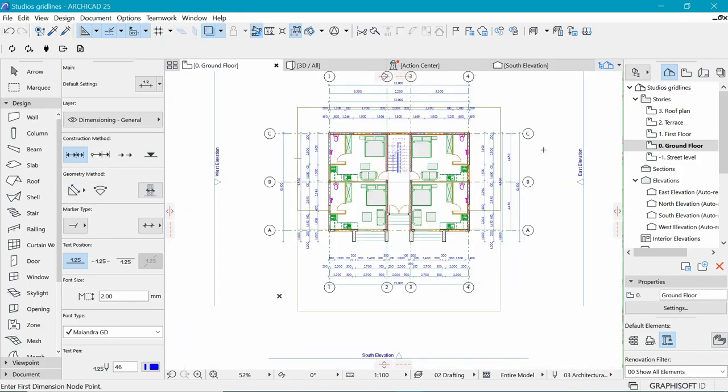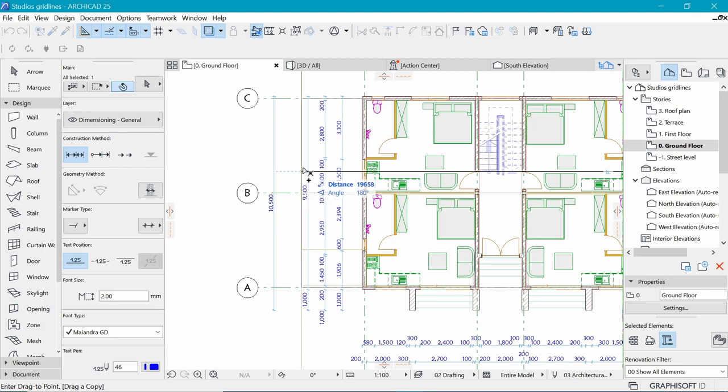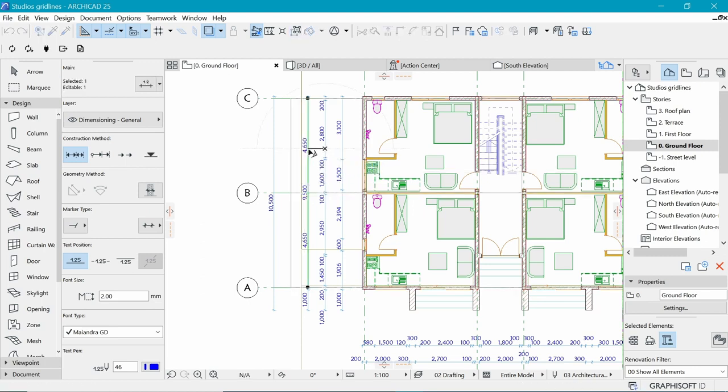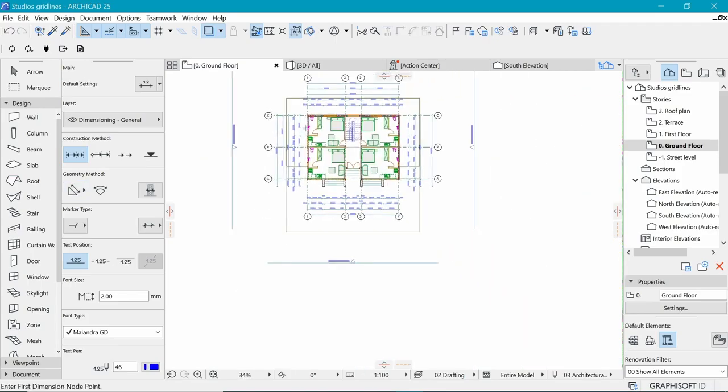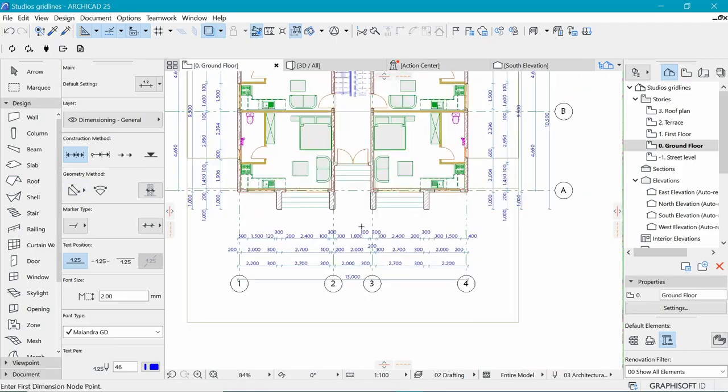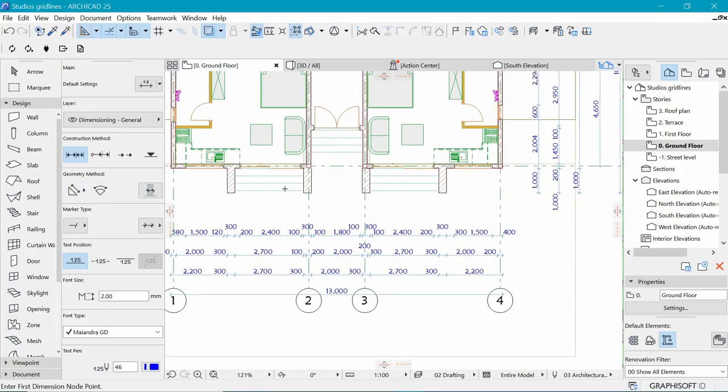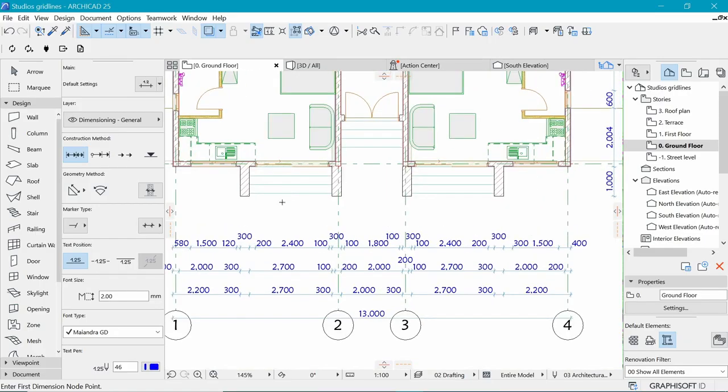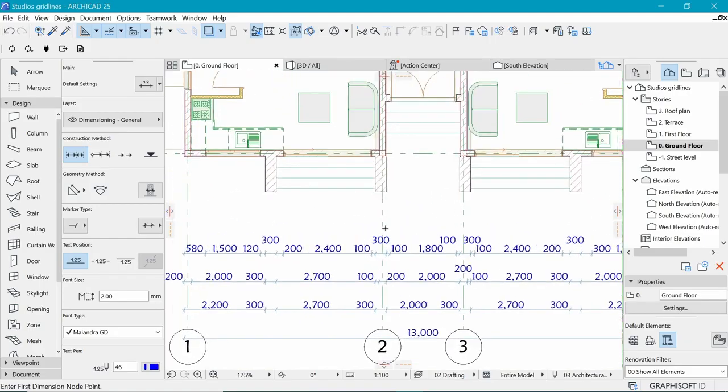So we can actually make a copy of this, Ctrl+Shift+D, in order to drag this all the way to somewhere here. And in order to put it in the perfect place, I will offset it from here by the 800. Okay, so that's good. And then the front has a lot of stuff going on here. So here we have 300, and we want to have 300 here.